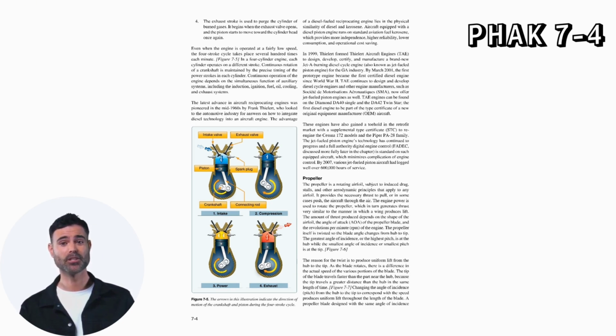The jet-fueled piston engine technology has continued to progress, and a full authority digital engine control (FADEC), discussed more fully later in the chapter, is standard on such equipped aircraft, which minimizes complication of engine control. By 2007, various jet-fueled piston aircraft had logged well over 600,000 hours of service. Propeller. The propeller is a rotating airfoil, subject to induced drag, stalls, and other aerodynamic principles that apply to any airfoil. It provides the necessary thrust to pull, or in some cases push, the aircraft through the air.